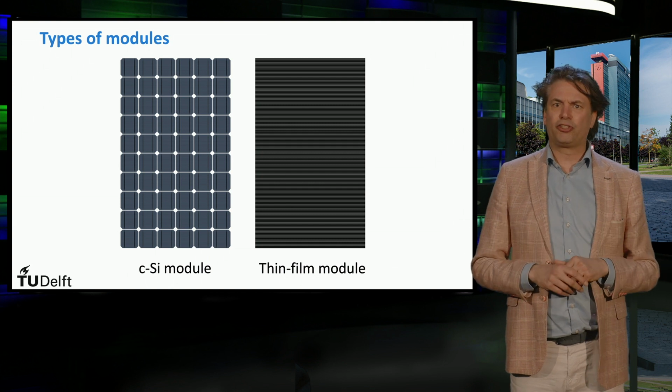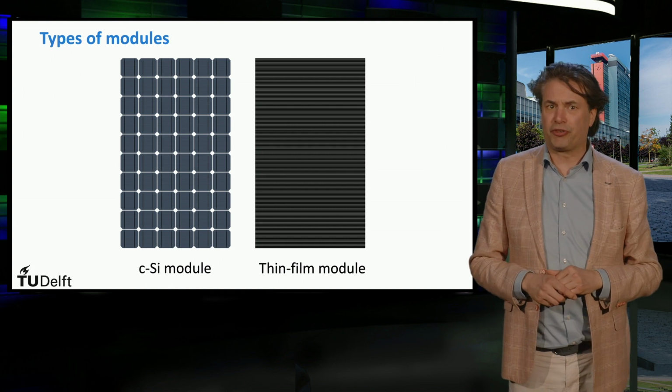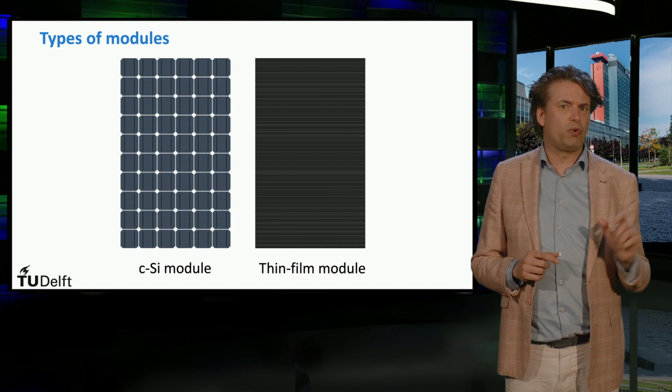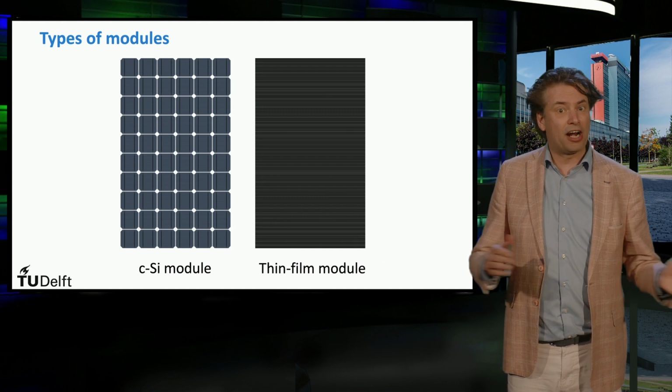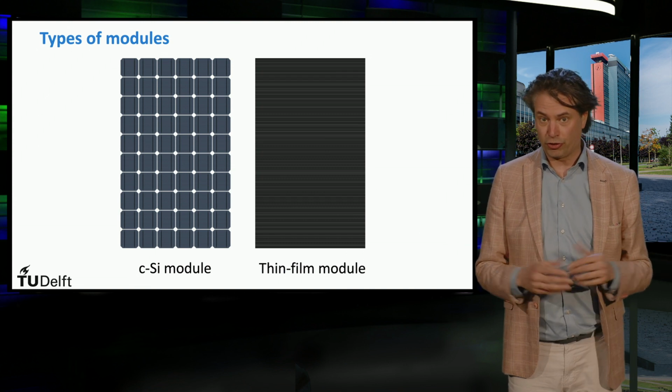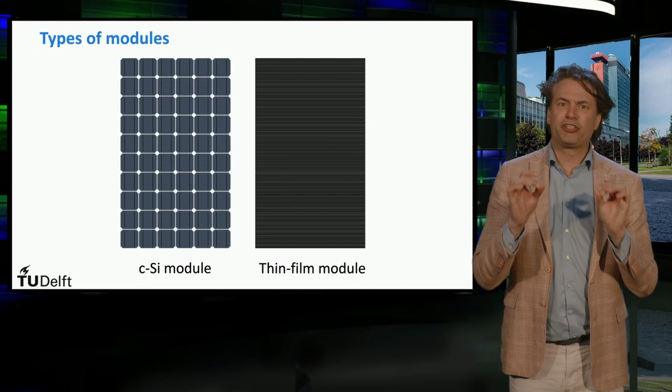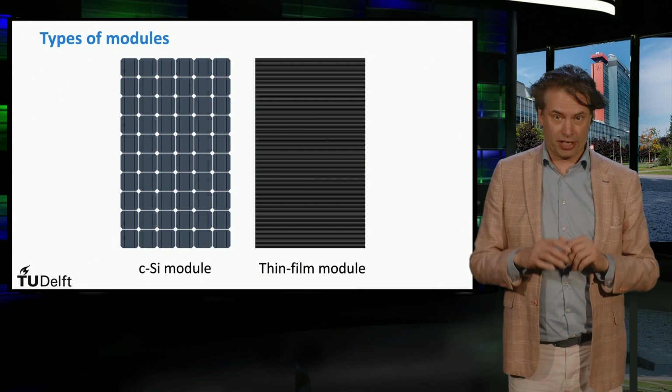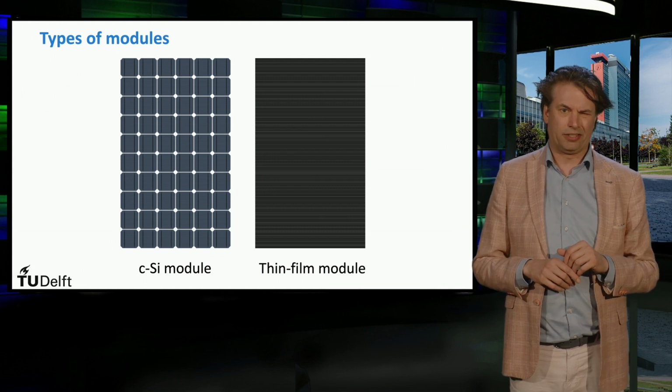The typical dimensions of a single solar cell are usually a strip with a width of 0.5 to 1 centimeter and a length of half to 1.5 meters, depending on the width of the PV modules themselves. The individual cells are monolithically interconnected, as will be discussed later.